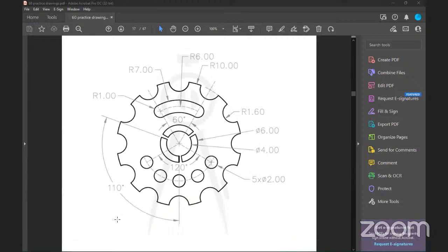So you look at the dimensions and get acquainted with them. You notice that some of them are of radius, while the others are diameters. So this is a symbol for diameter, while the arrow is a symbol for radius. Now, if you look here, you see that it's showing you this part to be radius 10. It means that this circle goes all the way around, and it was a full circle before they did some housekeeping, like trimming of some things, and made it look like this shape you're seeing.